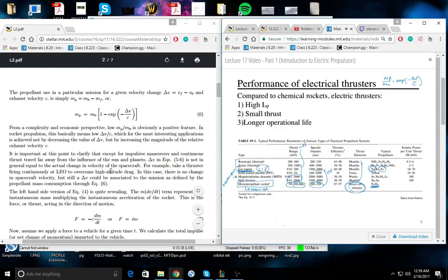Yes. For the thermal engines, if you were to have, like, is that the maximum specific impulse that you can achieve, period? Like, if you had nuclear reactors superheating a gas? Well, here the problem is that you're heating up a gas, so materials cannot withstand temperatures higher than certain values. So even if you had more power to dump in there, you would be constrained by other types of limitations, which would be thermal limitations. Yeah. So that's just materials limited. Yeah. In this case, yes, it's the same as for a combustion chamber. You're limited by materials.